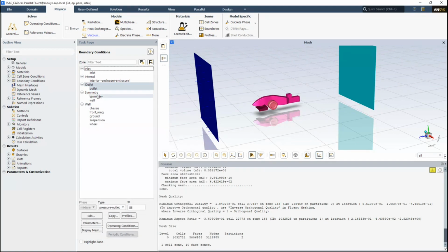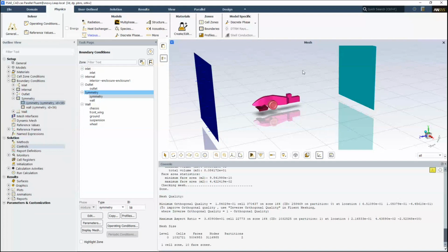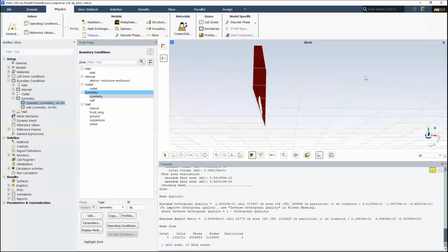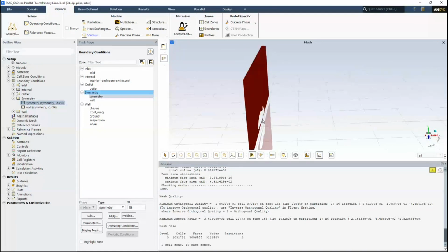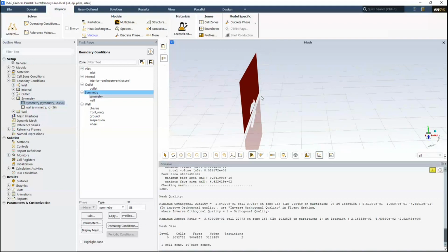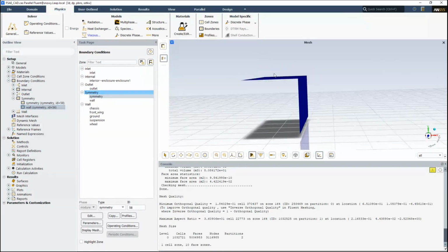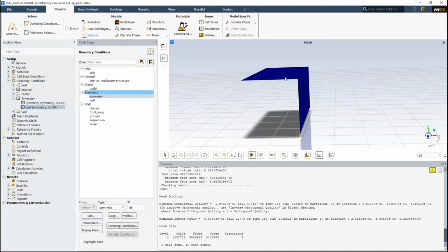And here we've got our symmetry. Our symmetry is obviously on the wall of symmetry, on our symmetry plane. And basically that just means there's 0 gradients at the wall here, and there's no friction from the wall on the airflow. Okay, you can go into the help file if you want a better understanding of the theoretical representation of a symmetry wall. I've actually put symmetry on all the other walls as well. Basically, I just don't want these walls to interact with the flow.